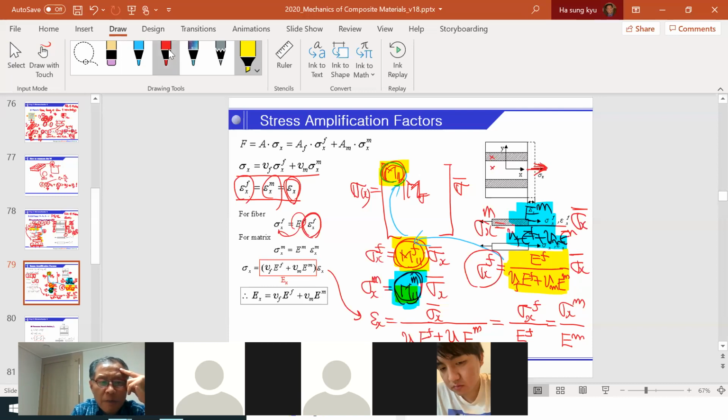The main purpose of the stress amplification factor is that, let's say you have a resin strength, you can compare and calculate whether the resin will fail or go into a plastic zone or plastic behavior, because this is the stress we're going to have in the resin for the given on-axis stresses.